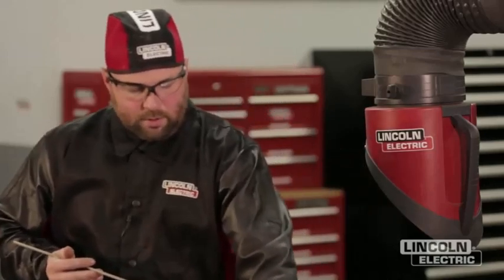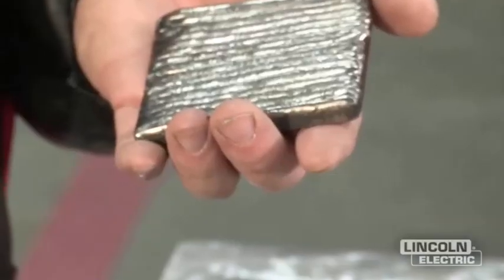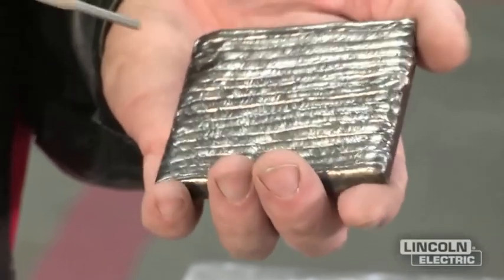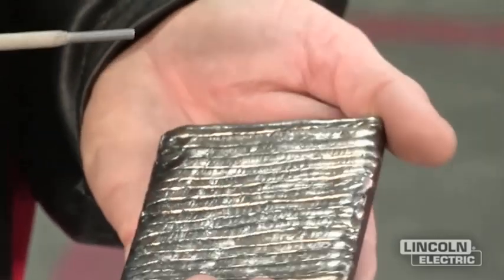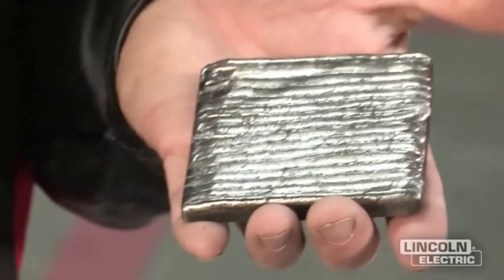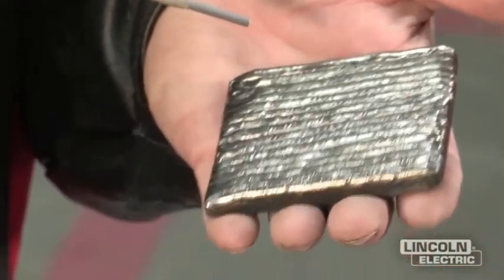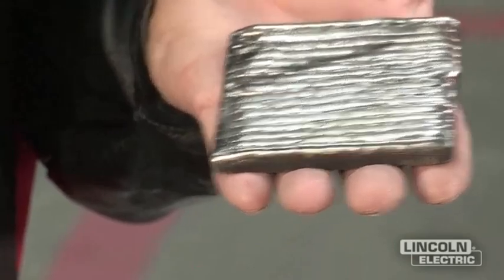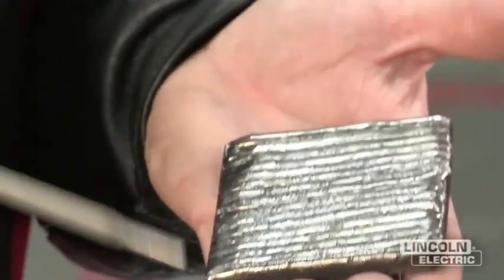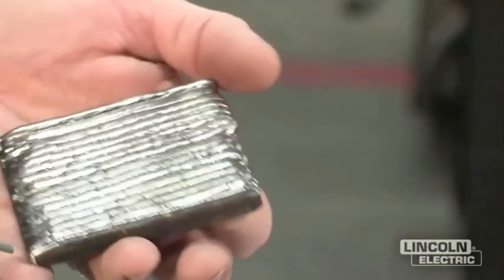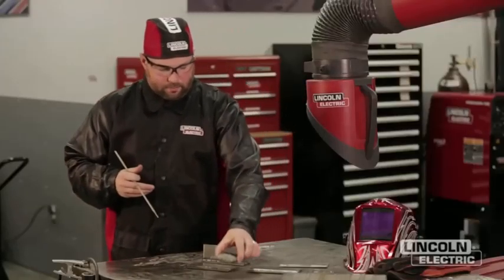The other one is that you're looking for the weld to be fairly uniform. By fairly uniform, we mean nice and straight, and you don't have places where it's wide and narrow, wide and narrow. For example, when you build a pad, the idea behind that is to get consistent, number one, keeping a straight line, and number two, making sure that they're consistent in width as you proceed down the pad. So a fairly uniform weld is also an important criteria to look for when welding.